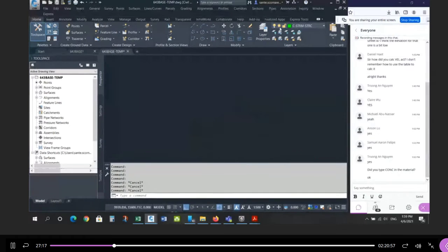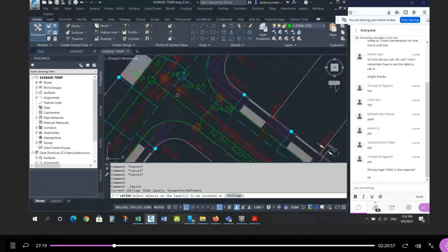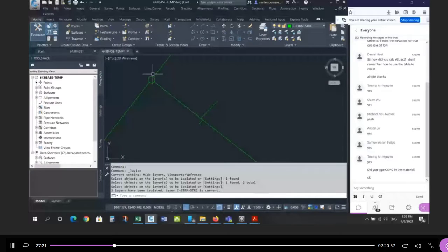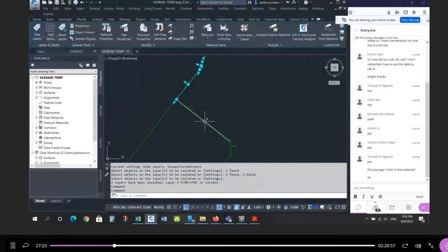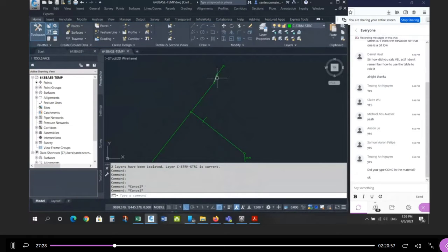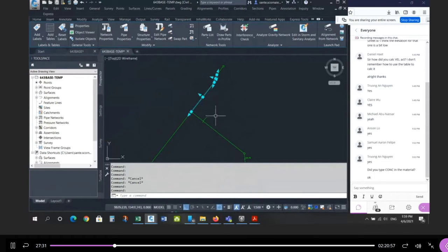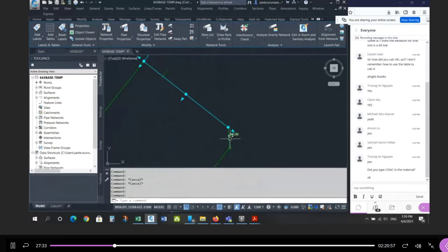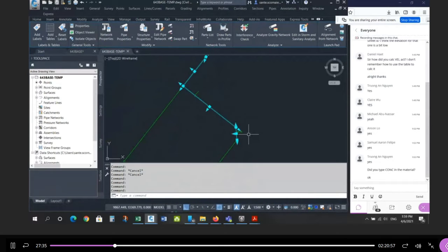Let me describe it one more time. Okay, so let me just take this and this again. So we're gonna make this pipe, and this pipe, and this pipe. These 4 pipes, right? Your design pipes, 1, 2, 3, and 4. We're gonna make them 0.25%, flatten them. And that will drive the sewer system down, much lower, okay?